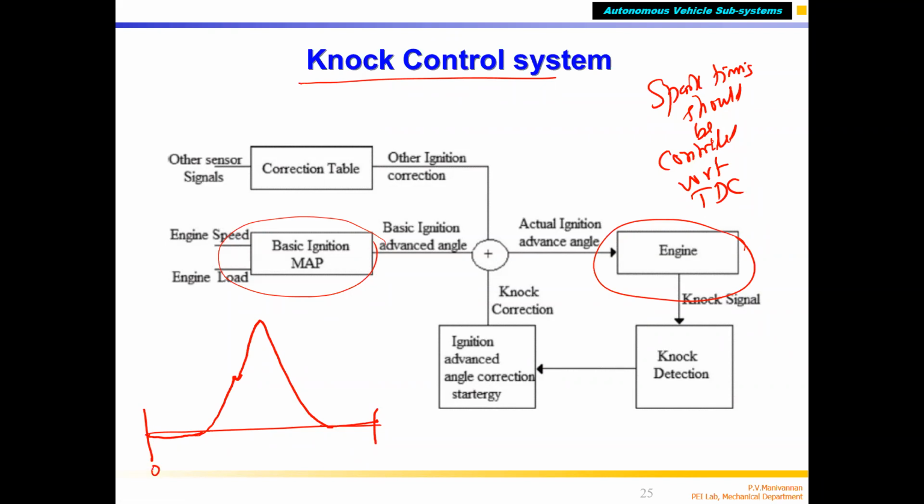So this is 0° crank angle, correct? This is 180°, this is 360, 540, 720, correct? We are talking about a 4-stroke petrol engine. So suction, this one. I am giving a spark here, correct? Fuel is injected here. In a petrol engine, fuel injection happens in the suction stroke.